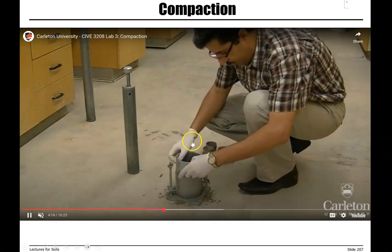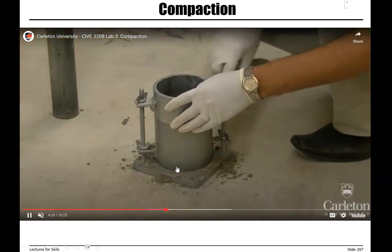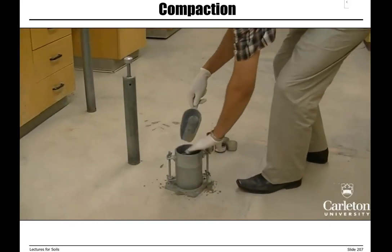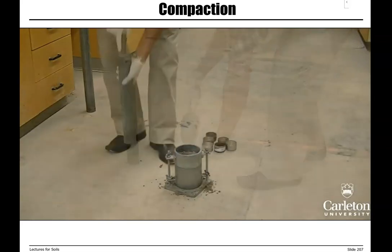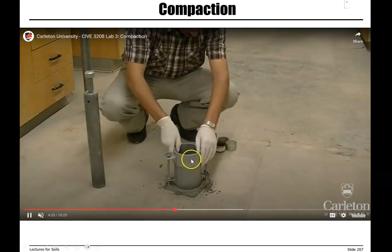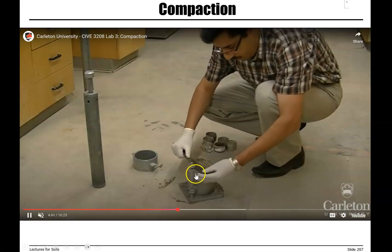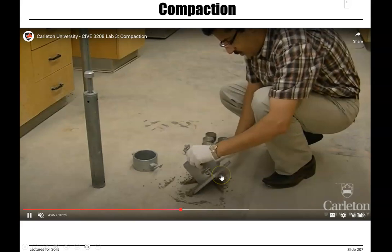Then you add your extension, add more soil, and compact the third layer of soil. Then you need to remove the extension and use a spatula to flatten the surface of your soil in the mold.